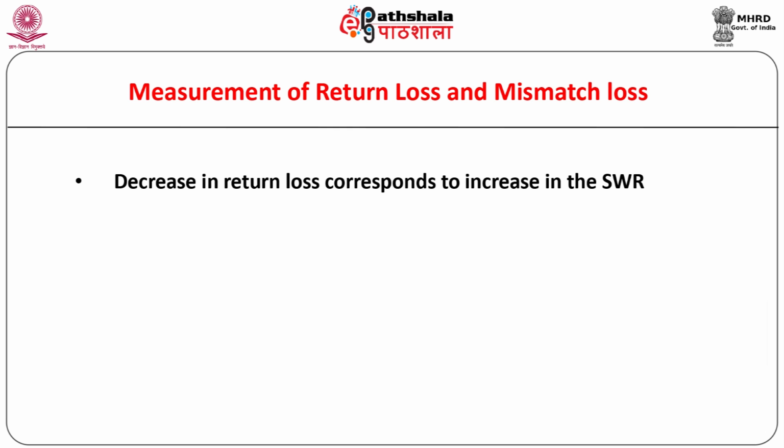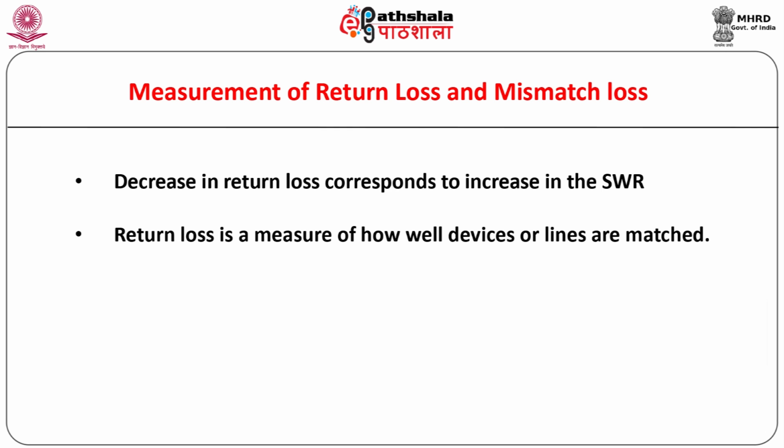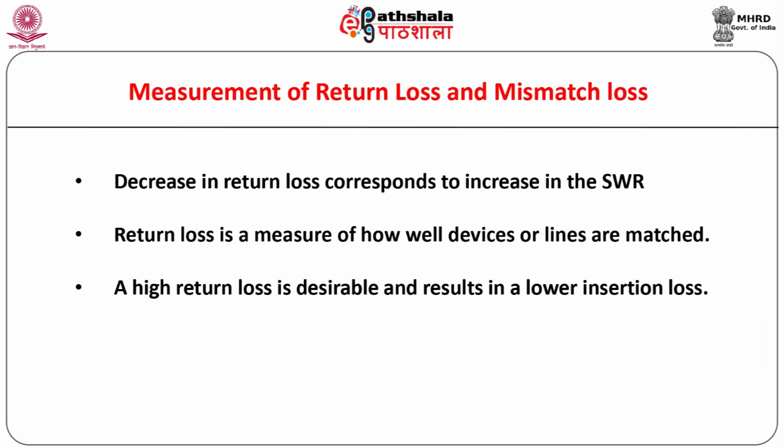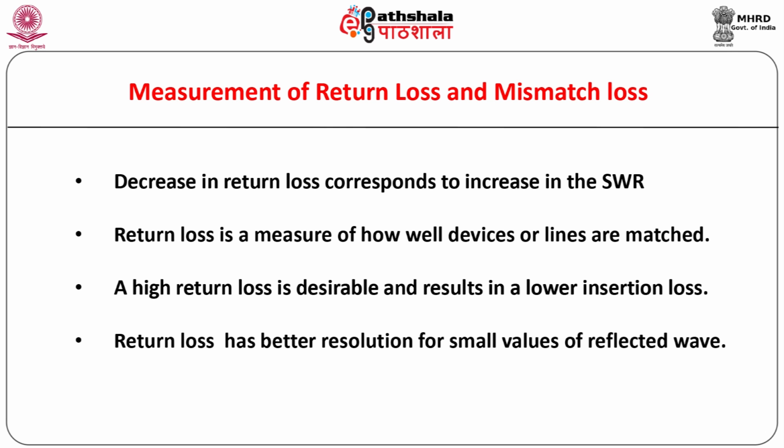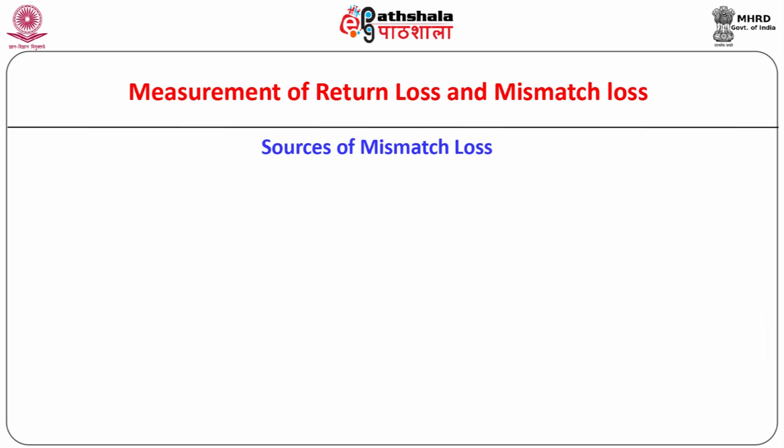Increase in return loss corresponds to decrease in the SWR. Return loss is a measure of how well devices or lines are matched. A match is good if the return loss is high. A high return loss is desirable and results in a lower insertion loss. Return loss is used in modern practice in preference to SWR because it has better resolution for small values of reflected wave.